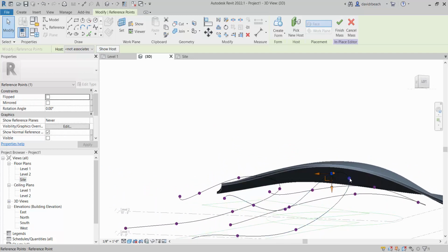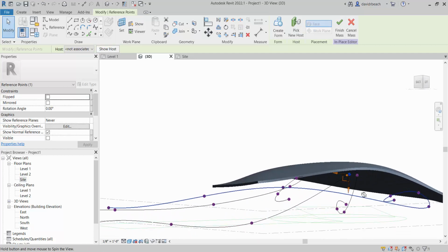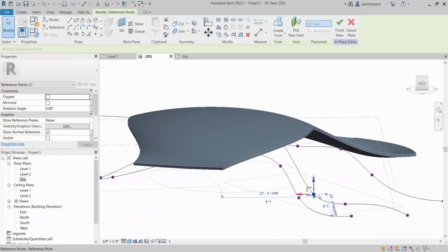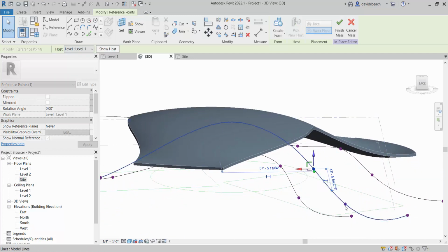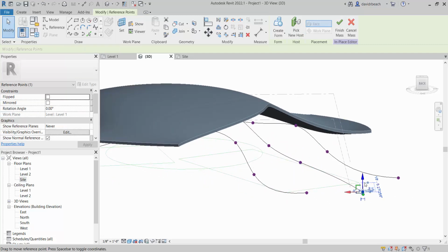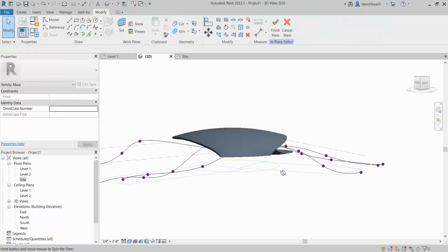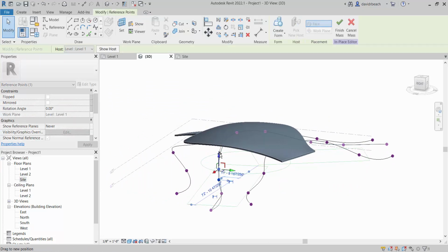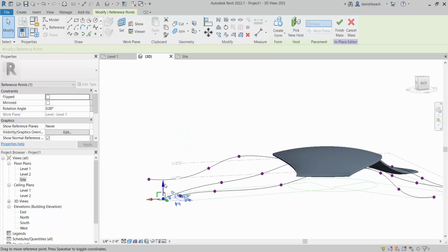Essentially, when you snap to something in Revit, it's going to assume those two things are connected, and you always want them to be connected forever and ever. In this case, I really didn't want that. What I was looking for is those to be on the ground plane and be able to move them up. So let's hope here, in terms of recreating this, that I actually have that massing form not wrapping around in itself again. That would be great.